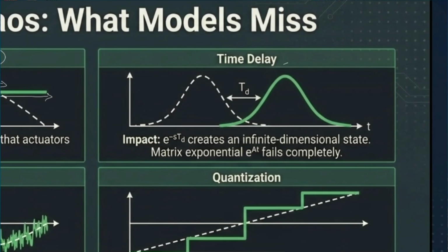Another thing would be the time delay. Obviously, because of all of those connections, some kind of time delay would happen in the feedback loop, between the command signal that you give to the system and its response. You would have this small amount of time delay, and this time delay could ruin everything.